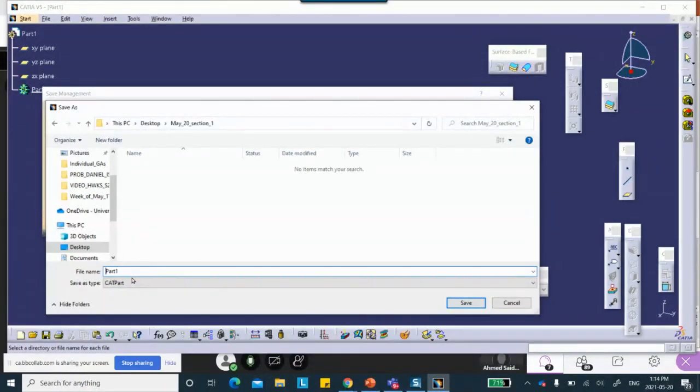And we make a Word file at the end. We say, oh, I know the name of the Word file, I want to change it. So you go right click, rename, and put the new name. Or even worse, you open it up and say save as something else. That does not work in CATIA. You can do it, but when you send us your work, your analysis file cannot find out where that part is, okay? Because you renamed it. It doesn't know that. Use file save management.